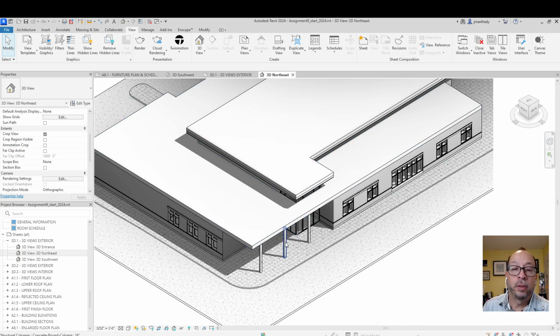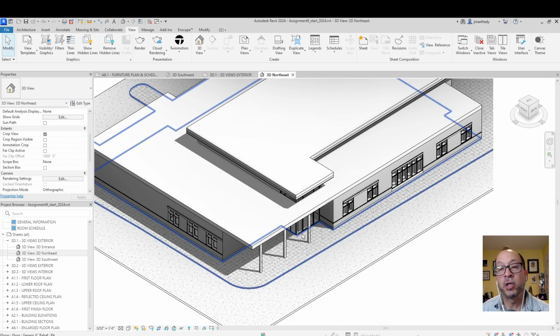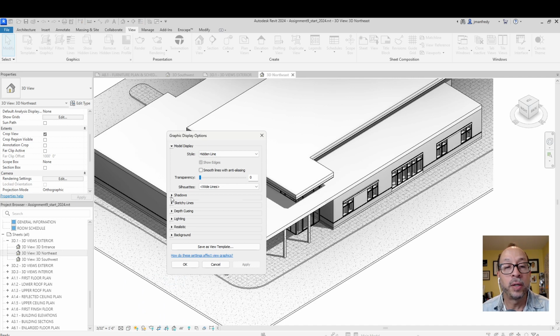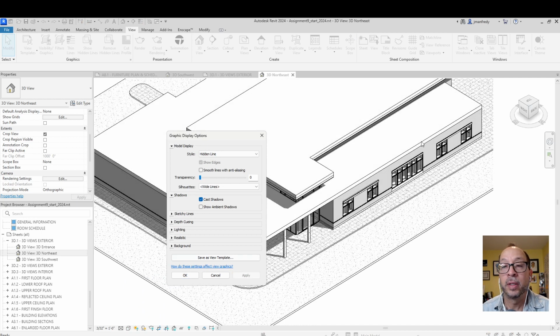But where do those shadows come from, and how can I change them if I needed to change them? You can actually have a method of changing those shadows. Well, let's continue on this list for a second. So shadows. Do you want ambient shadows? Yes or no? You can have one or the other or both. If I turn off ambient, it looks like this. It gets brighter. If I turn it on, you see this little soft shadow shows up around the model.